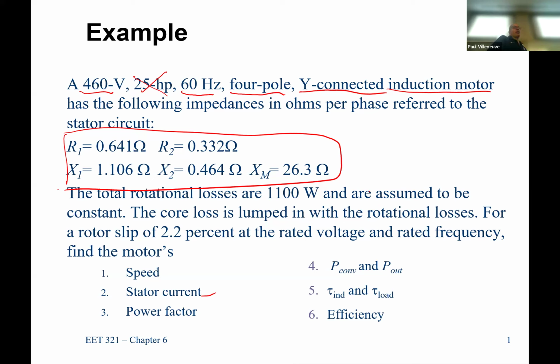It's not necessarily what it's producing. It's what the capability of the machine is. So you would need to know what the mechanical load requires, and then you would specify it. This thing can put out up to 25 horsepower. As long as you have a machine that can exceed the requirement and operates at the same speed, then you would use this as a specification only.